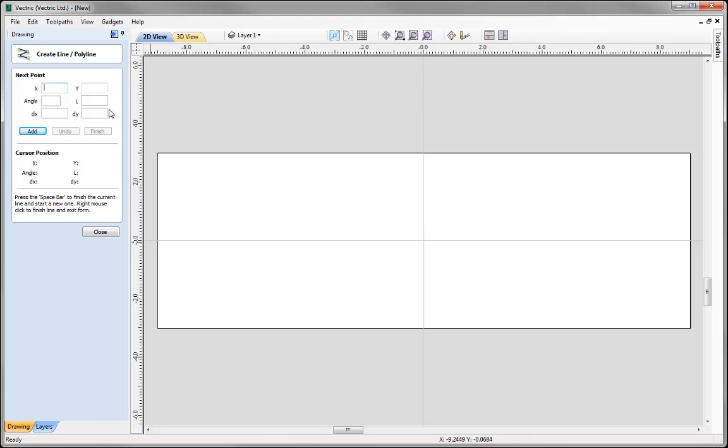So in the polyline tool, we can choose precise values where we want to start our first point, or we could simply just click at the centre point here, so I can see where my cursor is. It's at X0, Y0. I can see that we're in the centre as well because we've highlighted the vertical and horizontal lines for our overall job. So it's allowing me to snap to that centre point. So I'm just going to click here.